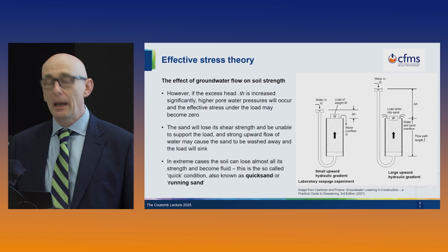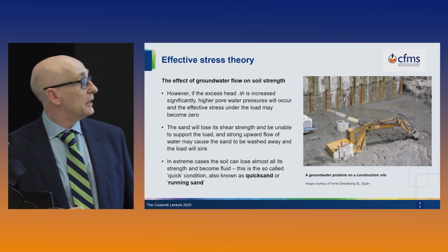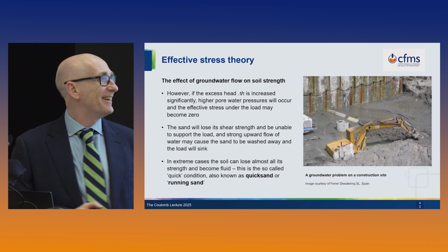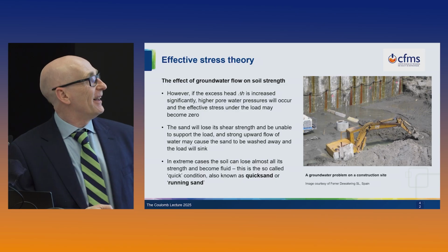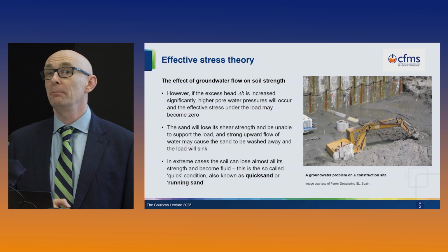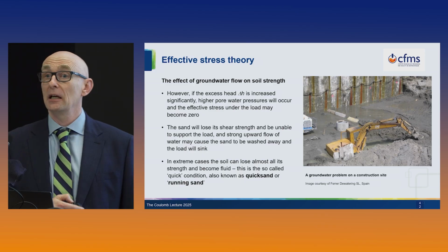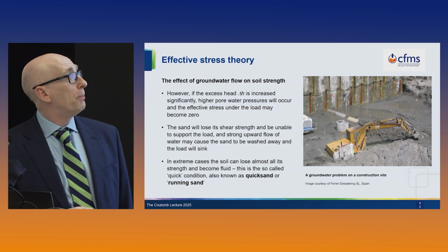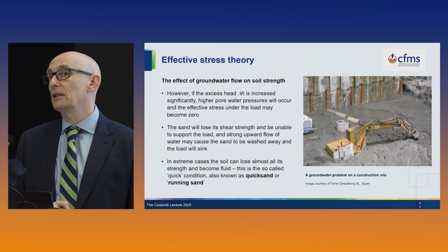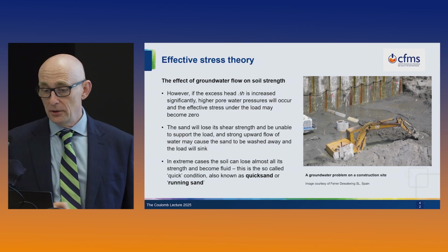And this all sounds very abstract and nice in the laboratory, but it can occur in the field. And what you're looking at here, and I should stress this is not one of my projects, an industry contact of mine very kindly sent me this picture. So this excavator probably weighs about 15 tons, and obviously at some point it's been sat in the bottom of an excavation that has walls around the outside, so the sides are nice and stable, but in this case the bottom has achieved a situation where it could not support the weight of the excavator, which has quite a low bearing pressure anyway, and it's sunk into the ground.